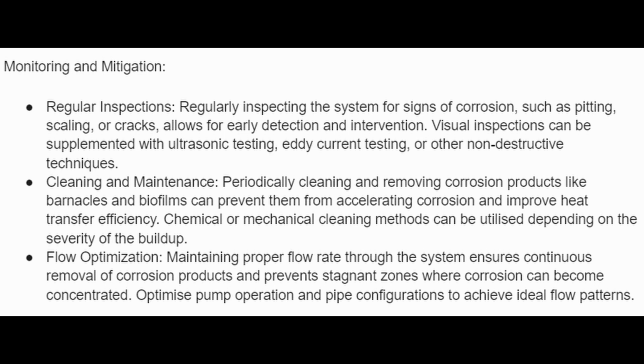early detection and intervention. Visual inspections can be supplemented with ultrasonic testing, eddy current testing, or other non-destructive techniques. Cleaning and maintenance. Periodically cleaning and removing corrosion products like barnacles and biofilms can prevent them from accelerating corrosion and improve heat transfer efficiency. Chemical or mechanical cleaning methods can be utilized depending on the severity of the buildup.